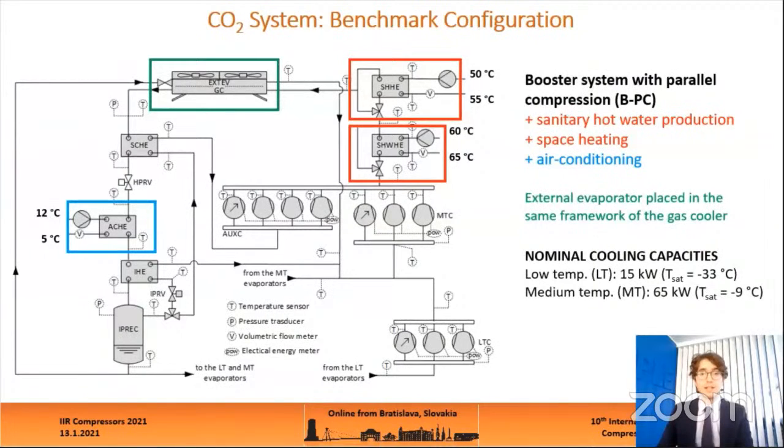An external evaporator is placed in the same framework of the gas cooler and at the same pressure level of the MT evaporators. It works during the winter time when the heat recovery is needed, absorbing a thermal heat flux from the outside, with no useful effect. This two-stage heat recovery requires the production of high-temperature water, and this may affect the performances of the system.